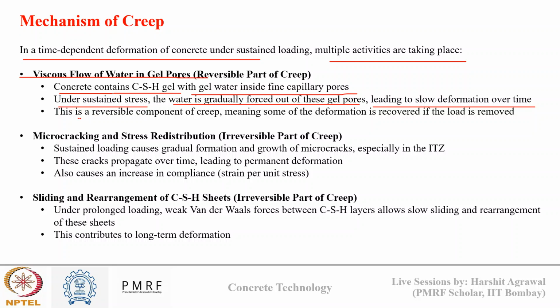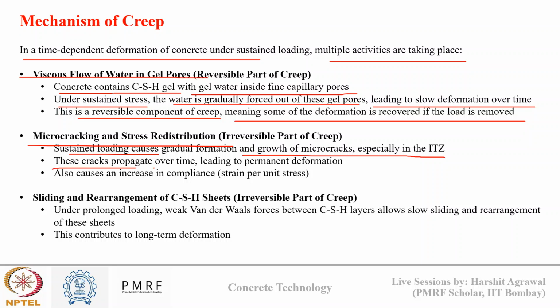So this component is reversible in nature. So some part of this component can be recovered when the loading is removed. Then second is micro cracking and stress distribution. Under sustained loading, we have seen that micro cracks will grow at ITZ, and these cracks propagate over time, which causes permanent deformation. And even if we remove the load, this strain can't be recovered. So that's why this is known as the irreversible part of creep.